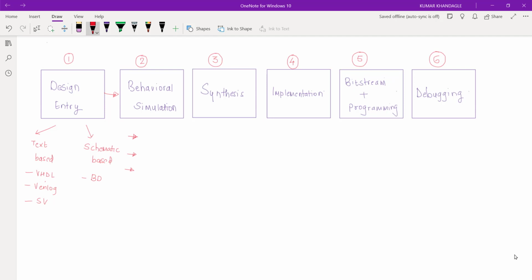Synthesis transforms our HDL code to something that our FPGA understands. It consists of nets and cells. Cells represent the primitives which are available for a specific device family. Something which we could do to optimize the primitives that have been invoked by default by Vivado is to utilize the settings, and these are the optimization strategies.